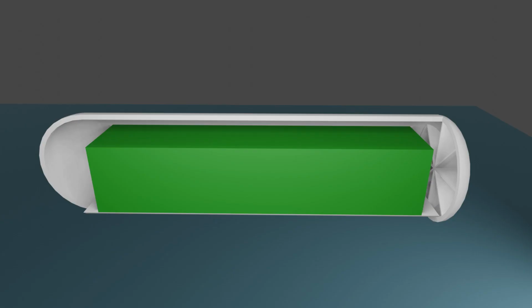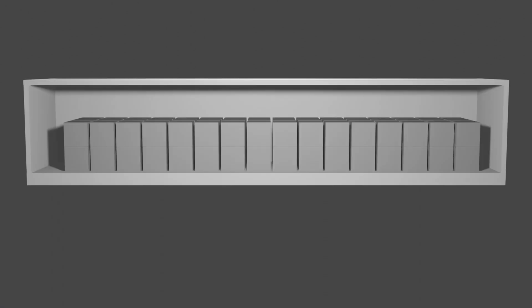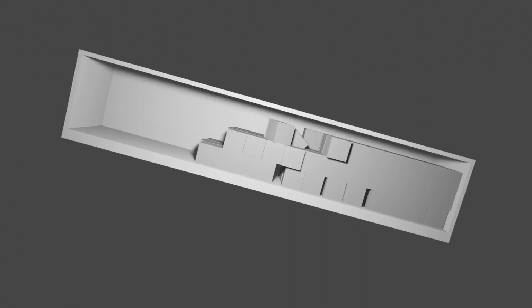You wouldn't want to use a standard cargo container because if the aircraft should, for any reasons, go to a high angle of attack, the cargo can shift backwards, and that shifting of weight could put the aircraft outside of its operational center of gravity, which would mean the airplane would then destabilize, fall out of the sky, crash to the ground, explode into flames, and everybody on board would be killed.